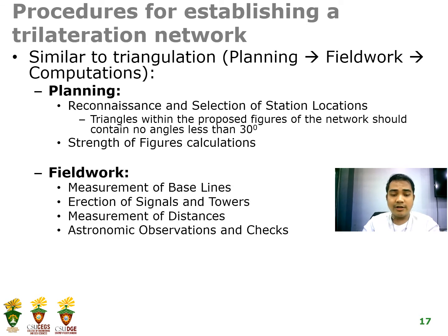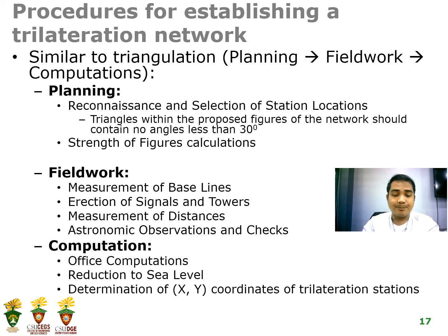And for the fieldwork rather, it involves the activities of measurement of baselines, erections of signals and towers, measurement of distances, astronomic observations, and checks. And for computation, it involves office computations, reduction to sea level, determination of x and y coordinates of trilateration stations.